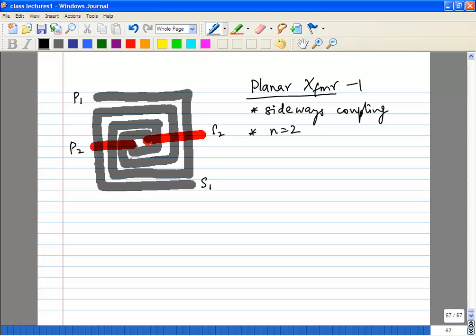And the other thing, of course, you note is that P1 and P2 are not symmetric. Similarly, S1 and S2 are not symmetric because now you have this on a lower layer or you have larger capacitance at this node, right? They are obviously not symmetric. Even though the primary and the secondary are symmetric, the 2 ports of the primary are not symmetric, which may be okay in certain cases.